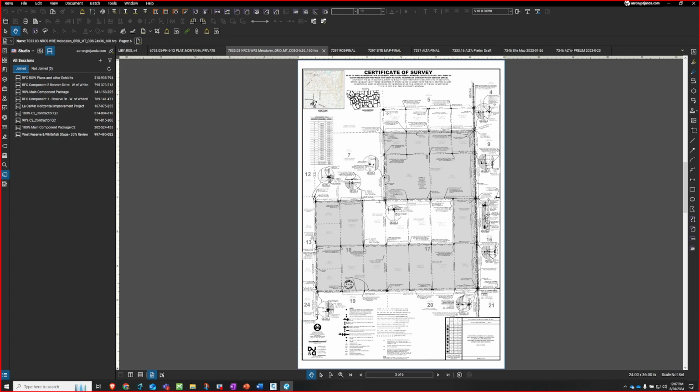I was going to say prior to annotative scale, we could change our text very quickly depending upon that. You'd have to make sure your scale was set when you set all your MText and all your dimensions, because if you changed it after the fact, then you're redoing a bunch of work. That's where it was really critical before we had annotative text. But again, visualizing and seeing where things are, so you know what text or scale style is the critical thing on this.